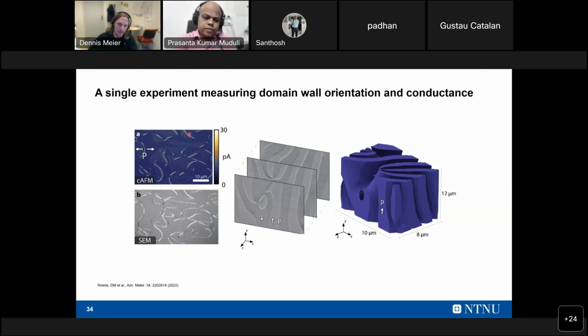You see here what's a bright wall in CAFM with enhanced conduction also appears bright in SEM. Then we have even these curved walls and shade features, and you see the very same is appearing in the CAFM. So you can normalize SEM measurements by CAFM so that you have information about the current signals and what contrast means. And once you have that, you can then mill through the system and really get layer by layer information about the structure and then reconstruct the 3D nature.